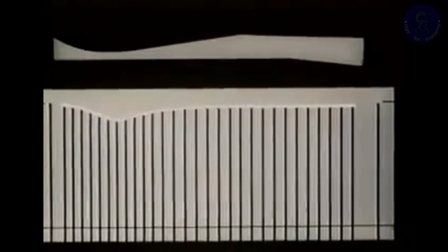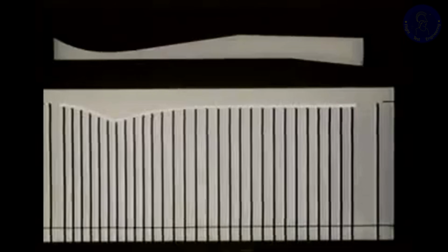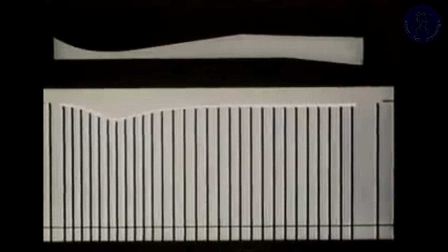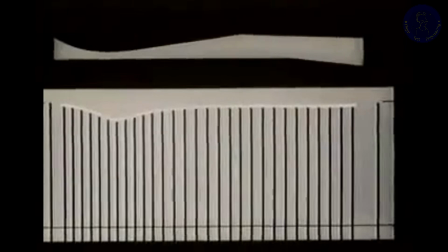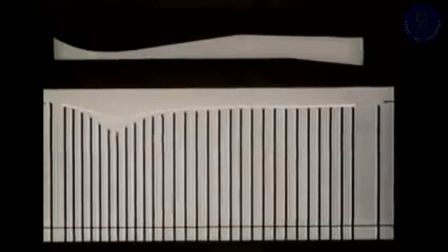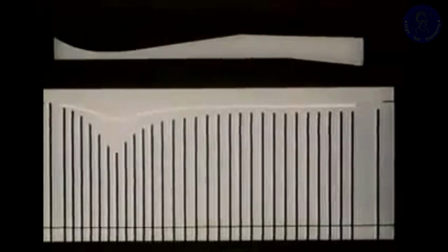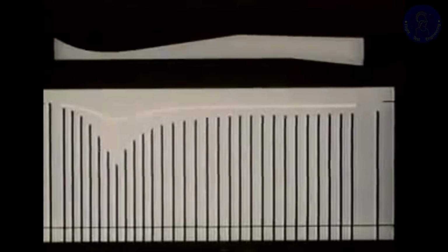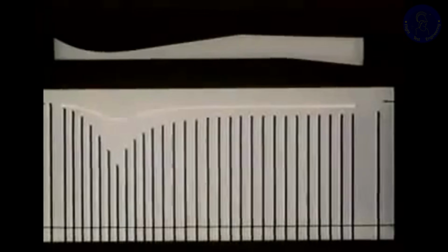This is because viscous forces are not important outside the boundary layers, and the fluid acceleration is determined by pressure forces alone. A falling pressure always means a rising velocity, and vice versa. The highest velocity in this flow is at the throat. If we increase this throat velocity, we come to a critical flow rate. The noise level suddenly changes, and the pressure distribution develops a corner at the throat.